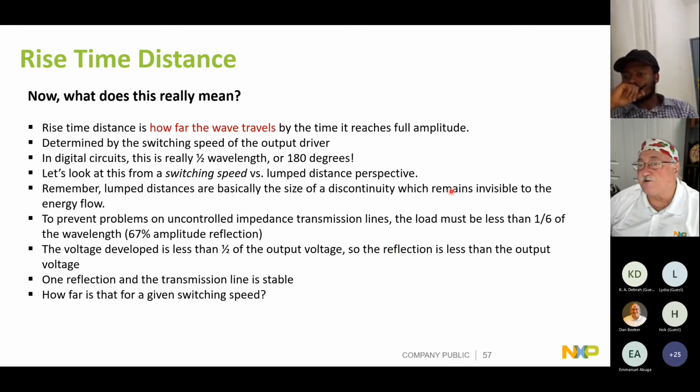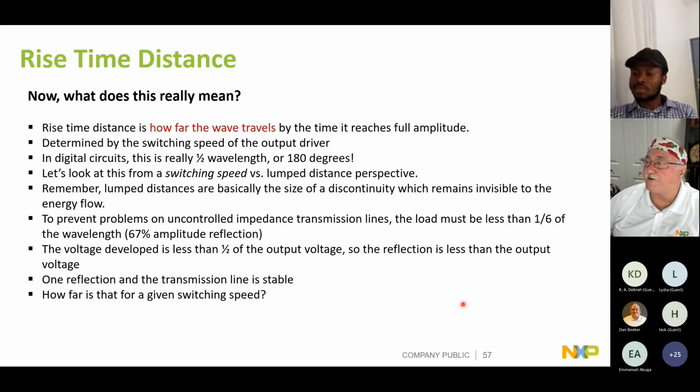And then you've got to have the resistor, and then you've got to drive it back down into the internal layers with a signal via and another ground via. So it really increases the complexity of your design. So that's one of the things you need to be aware of, and that's based on the transistor geometry of the driver.